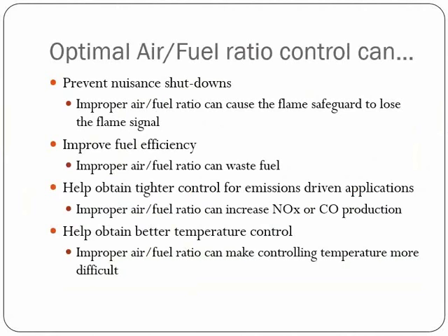Having an optimal air-fuel ratio can also improve your fuel efficiency. When you have a burner system that's designed and set up specifically to maintain a certain air-fuel ratio, whether that's excess air, excess fuel, or stoichiometric, that burner and the flame shape and geometry in that application is designed to give you certain velocity, mixing energy into your system, as well as temperature.